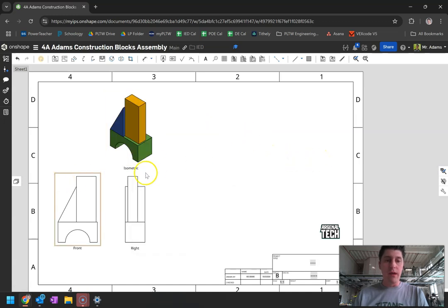So there is my multi-view drawing. I need to add those measurements that we have in the other version, so I'm going to use the Dimension tool to do that, which is right here. You can also press D on your keyboard. I'm going to set it so that the distance between these 2 lines is listed. And I'm also going to do the same here for these 2 dimensions from here to here. Those are the 2 gaps that we were asked to show.